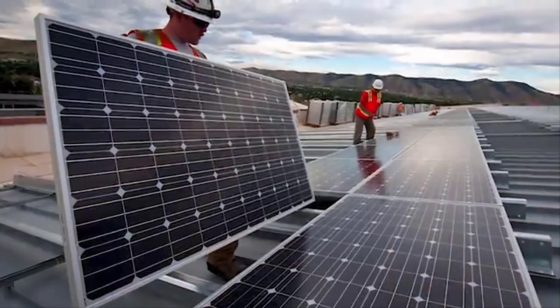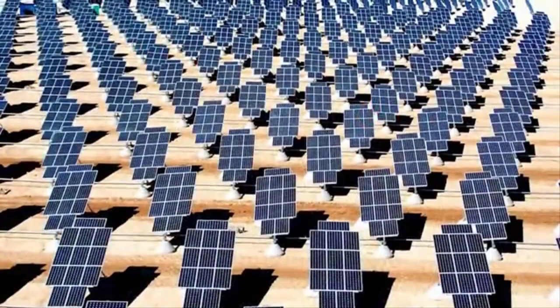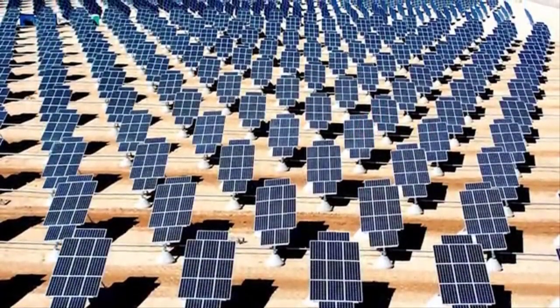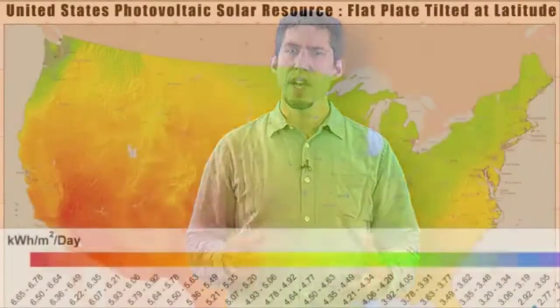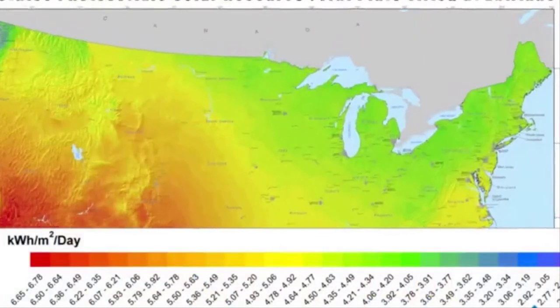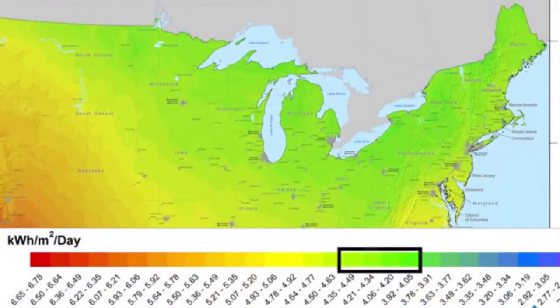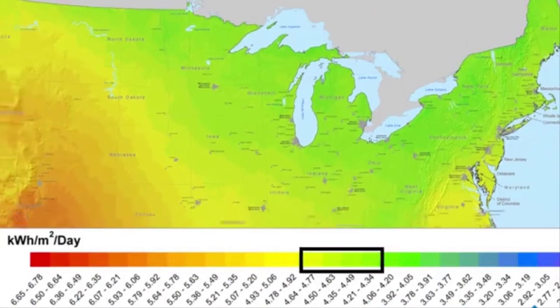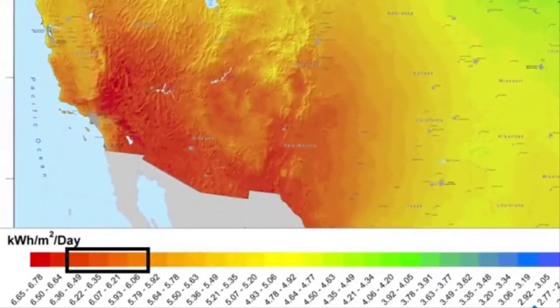Well, if you look at the popular press or news clippings, it might say a 10 kilowatt system was installed or a 1 megawatt system was installed. These kinds of numbers are talking about the installed power of the system. But remember, that power doesn't actually tell us anything about the energy that's produced. If we take that same size system and put it in the Northeast United States, it will produce less energy because there's less sunlight. Sunny areas in the Southwest United States will produce more energy. So this power rating gives you an idea of how much energy is produced based on sunlight levels.